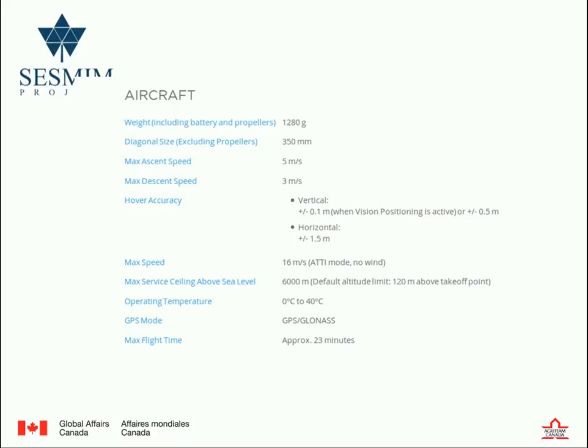The maximum flight time, this is based on the batteries, is 23 minutes. We think it's a lot less than that, probably. I wouldn't push it past 18 myself. So when we do the flight planning, we have to be 18. Yeah, I would recommend 18 because